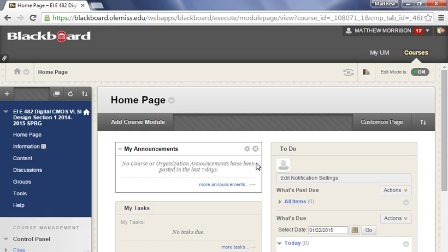What we're going to do is take a simple version of Verilog. All of you who took my course recognize the term MIPS. If you've gone through the textbook, you see that this course teaches an overview of a form of MIPS called multi-cycle. You can make simple Verilog code, which I'll show you how to do, and then you can take that and synthesize it. There's a free tool called Electric. You put it in, and it'll show you the chip, how much power you consume, the area, and the exact layout. I'll show you examples of Electric.